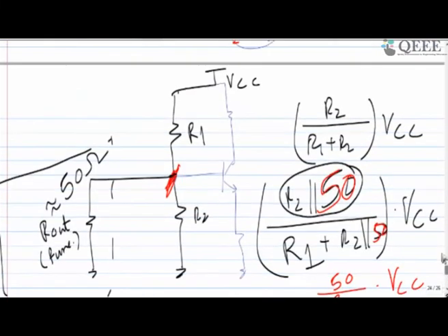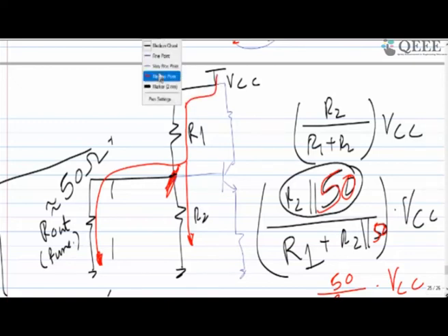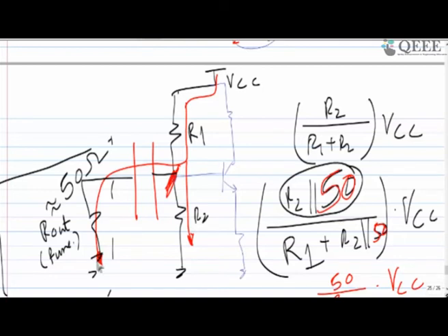So what my point is, if I want to block, because what is happening in reality, if you look at the current flow, it is actually divided on this side. Actually one current was also going this side, but I assumed that that current is not going. So there is current flow, or current sharing, between R2 and 50. I don't want that. The DC current which is coming from the top, what I can do, I put a big capacitor here and I block that current. If I block that current, I am going to see only R2. There is no DC current going from this side.